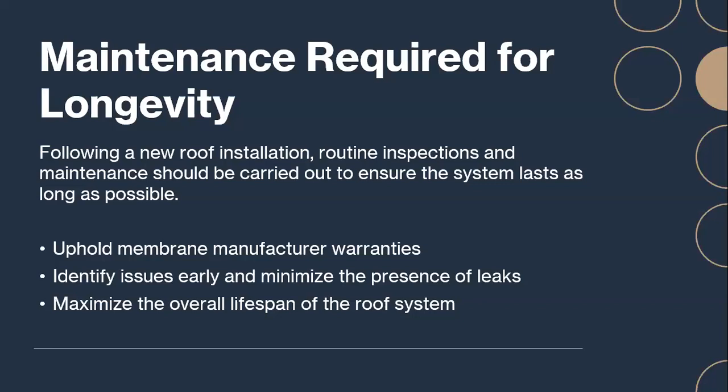Yep, we get this a lot. First and foremost, I would say one of the most important things, if your superintendent is going on the roof, is that he needs to stay far, far away from the edge of the roof. There's lots of tripping hazards on the roof. You're thinking you're staying within a safe distance, but all it takes is a small trip and you can go over the roof edge.